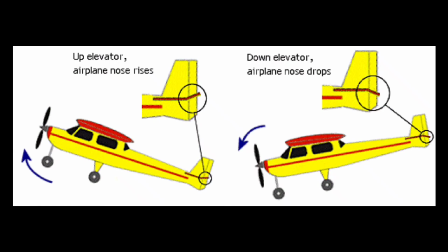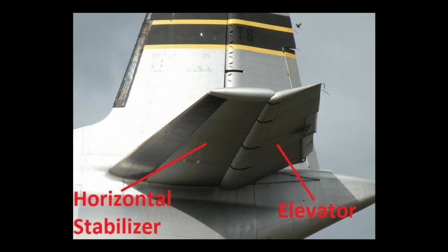However, pitching the nose up doesn't necessarily mean the plane will climb. In fact, it's quite possible to fly level or even descend with a nose up attitude. Only when power is added and speed increased will the plane climb with up elevator. Elevators are the single most important control surface of a plane, and they affect the airplane's airspeed more than the need to climb or dive.